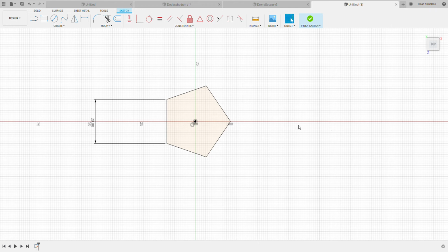All right. Then you're going to create another circumscribed polygon, starting there, tab 5 sides, lock that in, escape, get out of that setup, select the origin, and shift and select another point. Also constrain that. Alright, get back out of constraints,